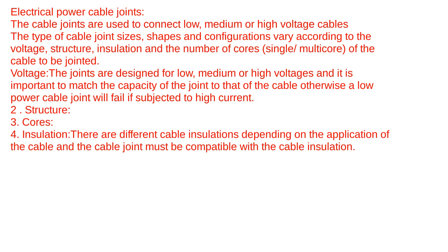To maintain the insulation of the jointed cables, there are a variety of insulation procedures that can be applied, and they can either be heat or cold shrinkable insulation. This includes the use of masking tapes. Once you have made your joint, you have your masking tape around that joint. That is very common. Most of us have encountered this. You join two wires and then you seal them off using a masking tape.